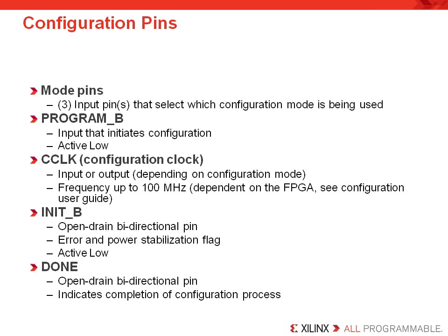As I mentioned earlier, the mode pins define to the FPGA the mode selected. There are 3 mode pins, and they are inputs to the FPGA. The program pin is an input pin that is active low. It initiates the configuration process. So if you're going to reconfigure the device after it has already been programmed, then you will have to toggle this input pin to start reconfiguration all over again.